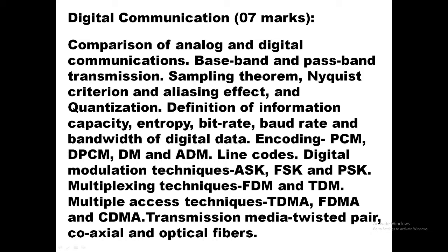If you don't follow the sampling theorem, if the sampling frequency is less than twice the highest modulating frequency, then you will face aliasing effect. Then after that you should know what quantization is, because you have already studied sampling and quantization, so you can convert any analog signal into digital. Okay, that is you can use your PCM, DPCM, DM and ADM types of modulation techniques.